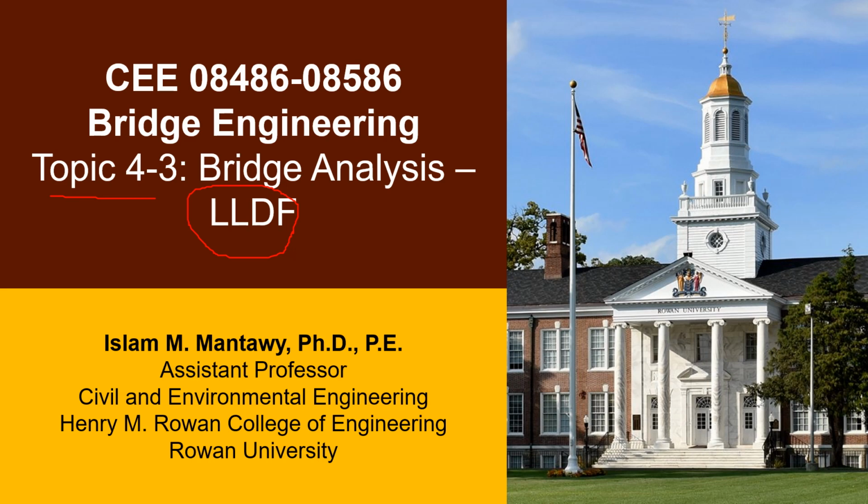we got understanding on how to analyze the truck moving along the bridge or the longitudinal direction in terms of two methods. The first one was influence line method. The second one is moving load method. We were able to see if we have a truck that moves over a simply supported span, or in some cases continuous spans, on how to get the reaction, maximum moment, and maximum shear.